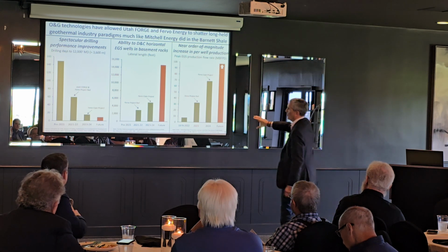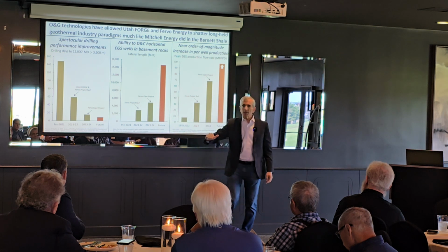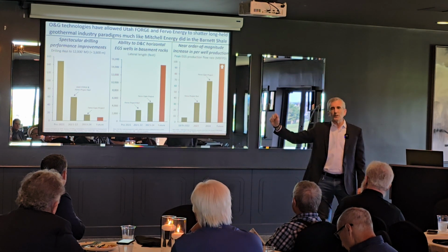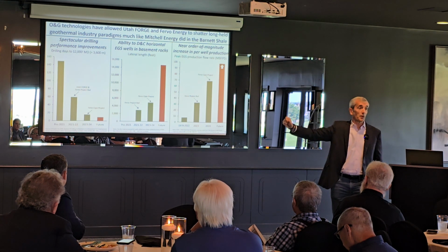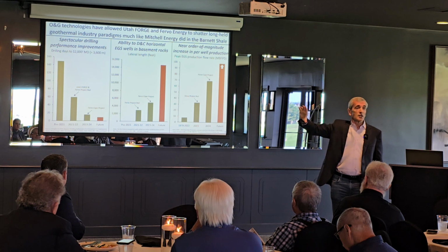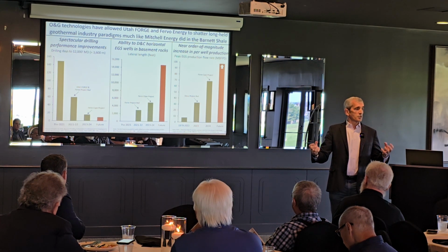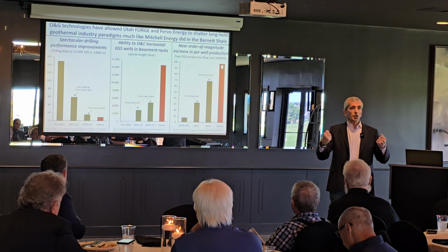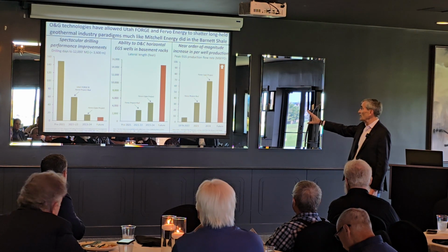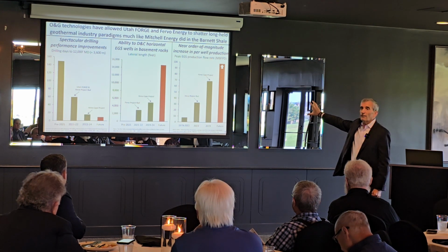And what's happening right now is much like what happened in oil and gas with horizontal laterals. We're extending the length. So we've gone from 3,000 feet to 5,000 feet. The next wells at Fervo's Cape project are going to be 7,500 feet. No reason to believe we can't start drilling wells that are 2-3 miles long. So the extension of those well bores, as you know, in oil and gas have led to incredible economic improvements. And you're seeing some of the same thing in geothermal. And then look at the graph on the right.